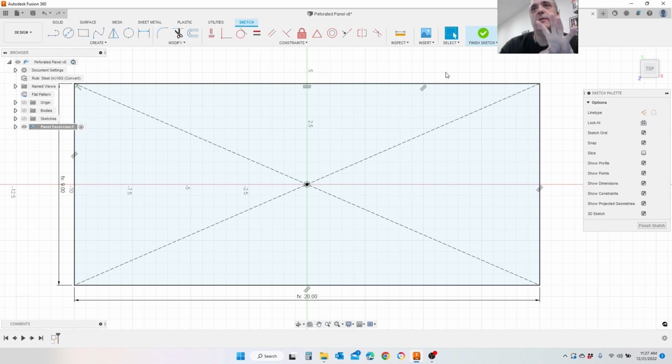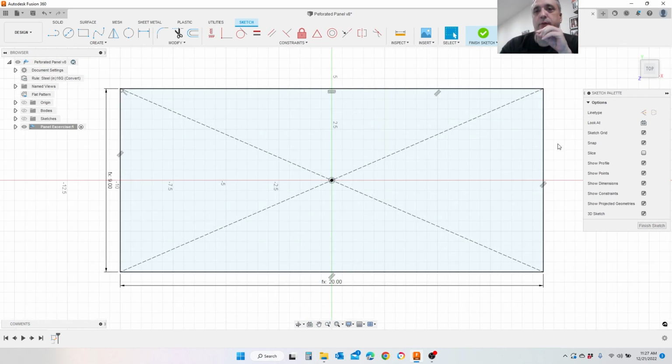So this is the interesting thing: when you bend things from a flat, you might not necessarily know exactly what the dimensions are going to be. They could be a little bit off a tolerance. That's why I always recommend, if you can, to do this part in a profile first, because then you're making it where you want it to be, where you want it to bend to, and then flatten it from there. But in this case, we're going to do the opposite. Sometimes going from a flat pattern to a bent product, it's easier to do more complicated type bends.